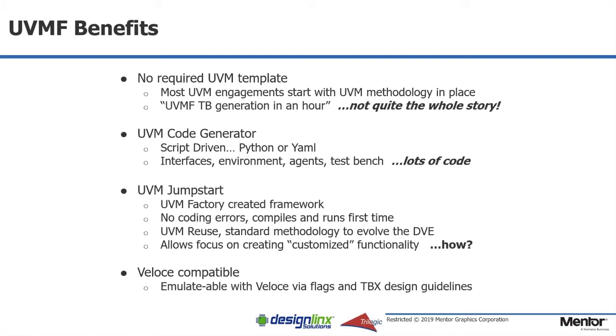So UVMF is really a jump start on UVM. The output is a factory-created framework. It's all UVM compliant coding. Out of the gate, there are no coding errors. It compiles and runs the first time.